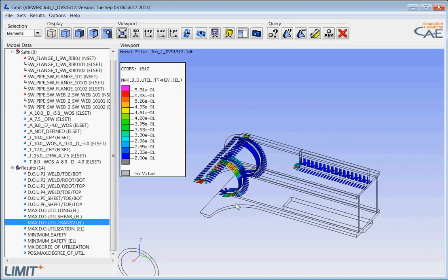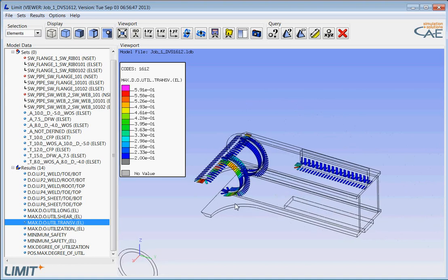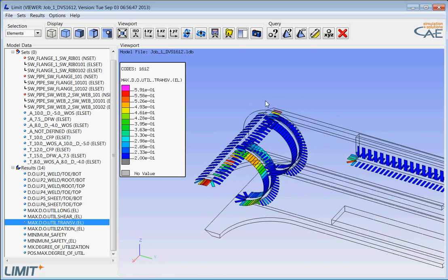For the sensors, we have the same possibilities as for shells. We can also use the query function. So what you do is you have to select the 2D elements because they are embedded in 3D elements. So if we pick elements or sensors, then we have to make sure that we hit the shell.